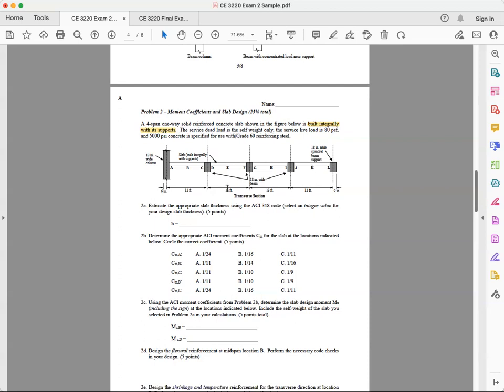So you look at this, and first thing is that they call it a transverse section, but not necessarily the transverse span. This is actually the longitudinal direction, but it's a transverse section because you're looking at the cross section right here. Now, if I look at this figure, the first thing I see is on the left side, this is a column. This is not an end, okay? This is a column. Why is this so important? Because if you recall, in the moment coefficient table, a very messy table a few weeks back, we talked about that. There were 3 rows.